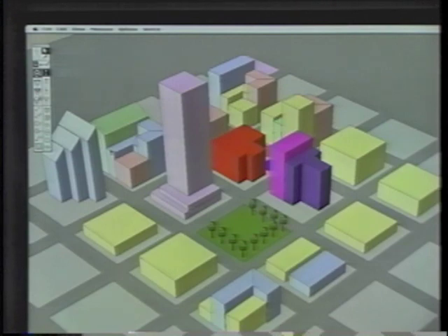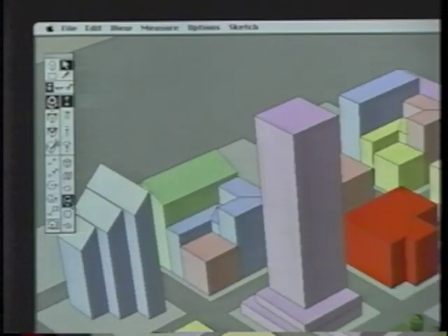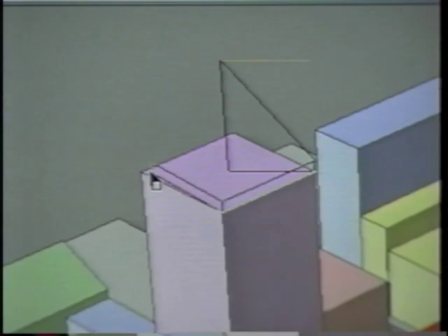To add our new element to this drawing, we'll select the Wall tool. Choose the ground plane by clicking on it. Click and drag for a height of the pyramid. Then select the corner points to enclose the shape, clicking at each corner point. When you complete the shape, the program shades it with a color which I've pre-selected.